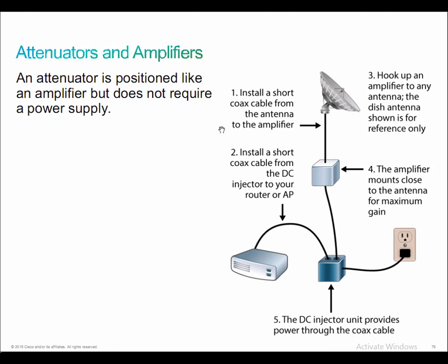But our goal is to increase the overall strength. So we're actually going to apply some sort of active process that amplifies the signal. Make sure that when you're deploying wireless networks that you comply with the maximum EIRP that's allowed in your area, governed by whatever governing body is applied in that particular area.